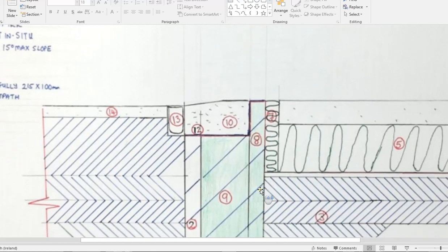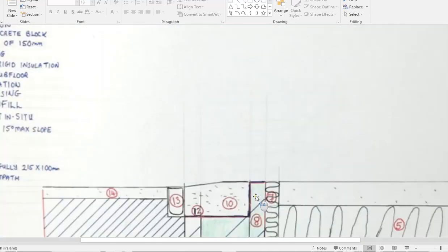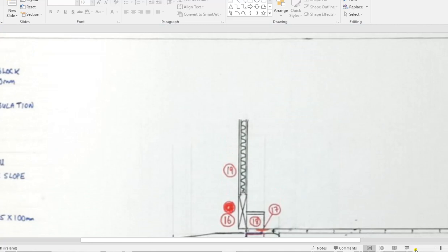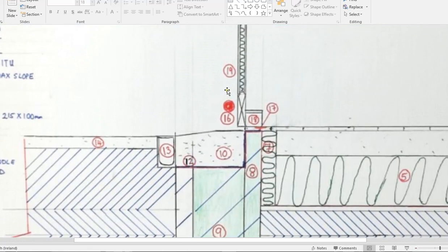Now the next diagram then that we'll look at is the finished section of the door. So the finished section of the door here, if we zoom out a small bit, so what we're looking at here is again brought down from the top of the door. So this is how we know if we have this drawn correctly. This section is brought down from the top of the top drawing. So what we have here is our base of our door. What we have is insulation inside in the center, and then our paneling at either side of the door.